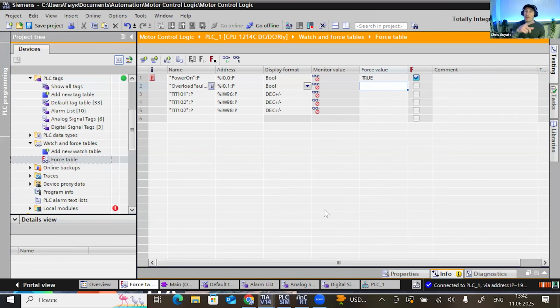We start a pump, but we haven't opened a valve later on in the hydraulic circuit. That pump could be building up a load of pressure against this closed valve, and it could cause a lot of problems. That's just one example. So when you're doing things like this in the software, you've got to be really conscious of what you're actually doing out in the field. Yes, correct.